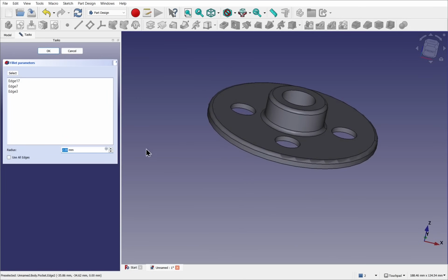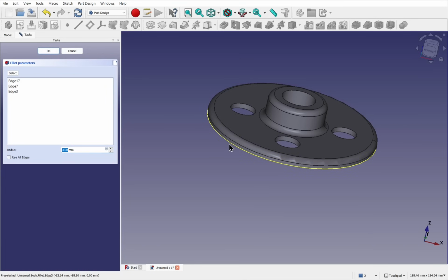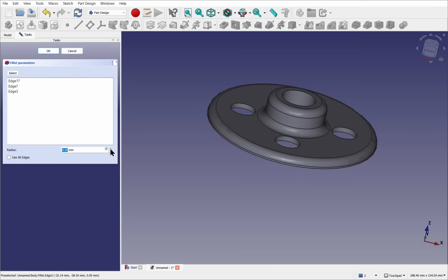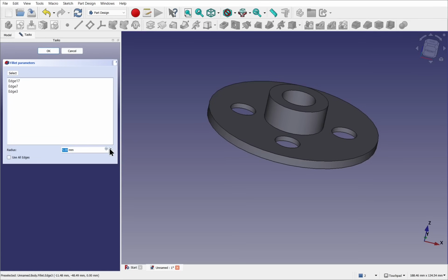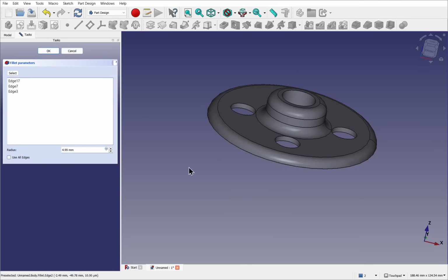There is one thing I want to go into with fillets. If I click on this fillet to bring it up to 3, you see the edge is being consumed. If I go further and it goes beyond this edge here, this opposite edge, it will fail. So if I need to fillet up to this edge here, this is a 5mm height here. This is set to 5mm. I have to back this off to something like 4.99, so it doesn't consume that edge there.